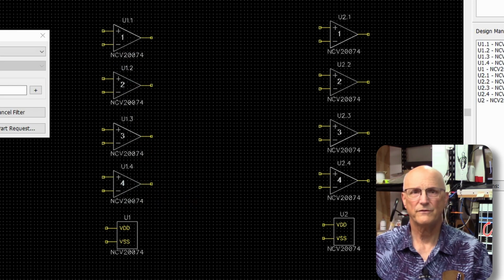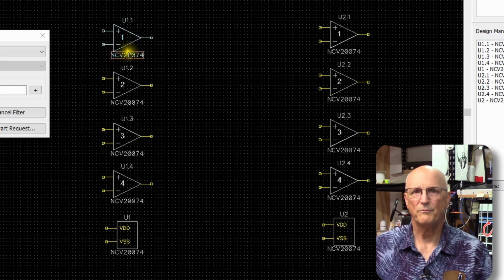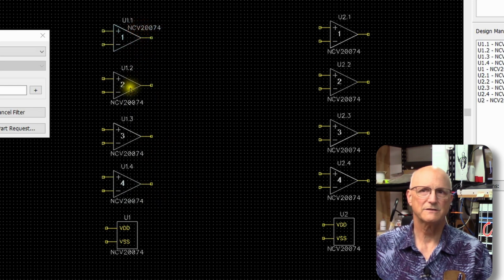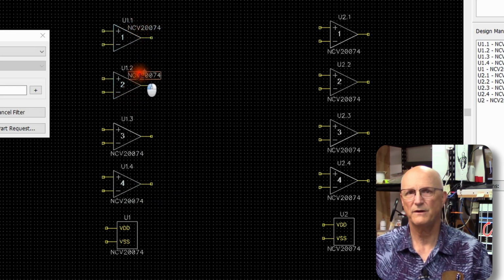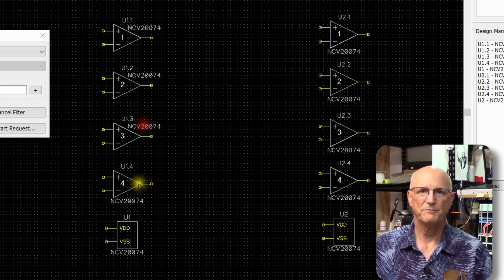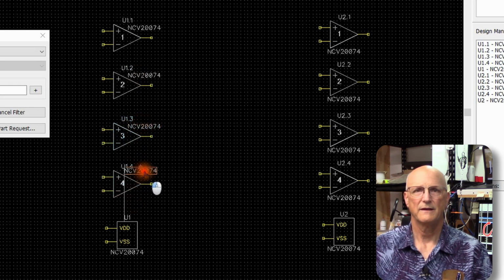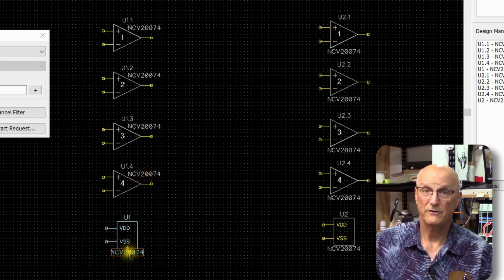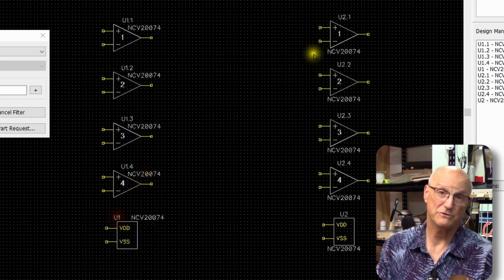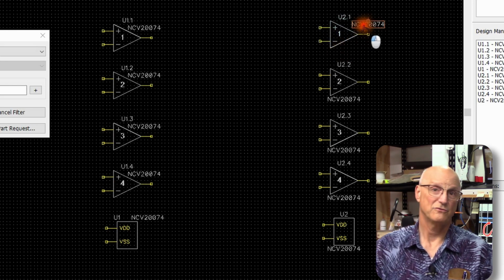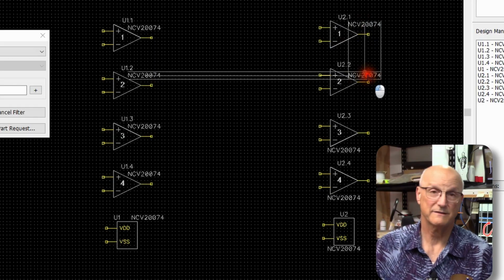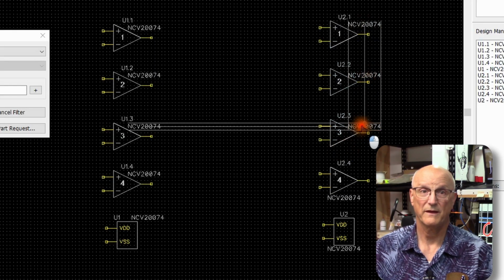When you hover over the text, a box will appear around the text. Click and hold on the text and drag it to where you want it to appear. When you let go of the mouse button, the text drops into place in the new location. Now, be aware that other text associated with the part may automatically choose to relocate. If you don't like where it goes, then just repeat the whole process on that text too.